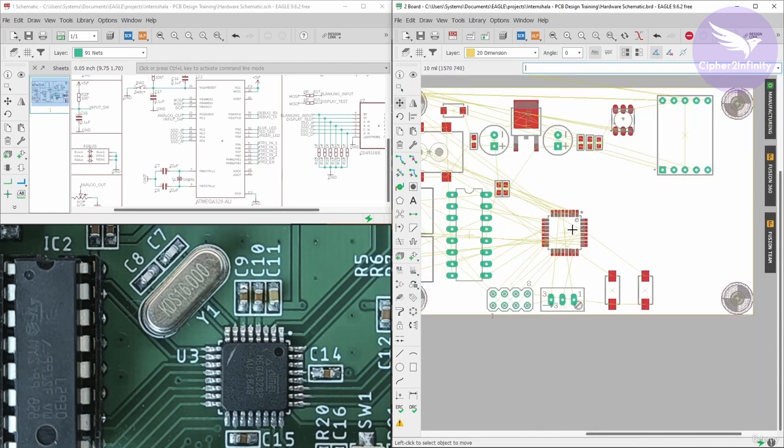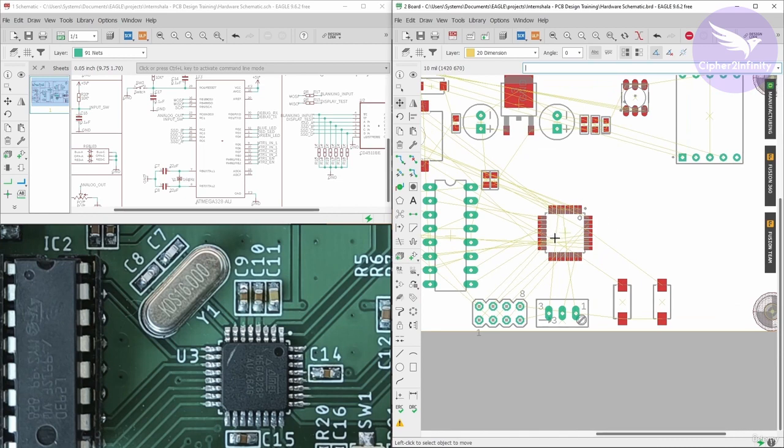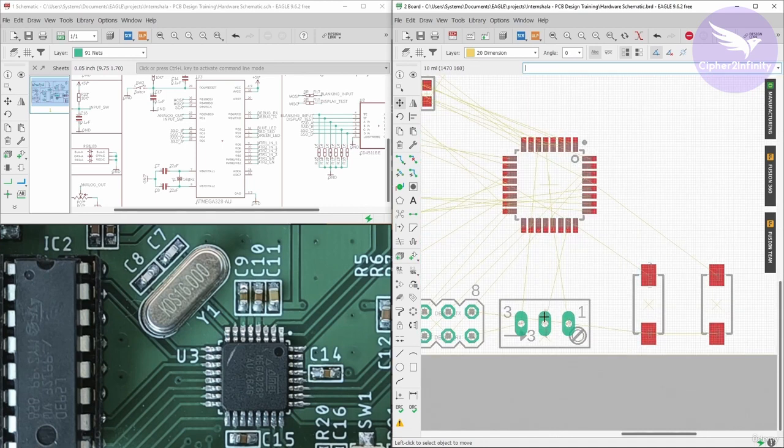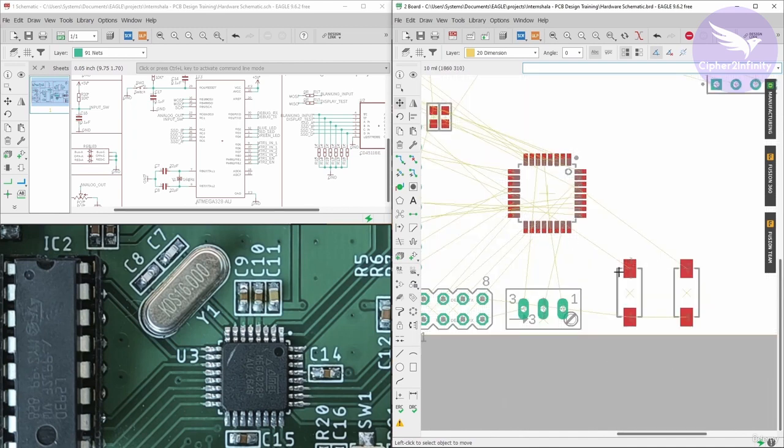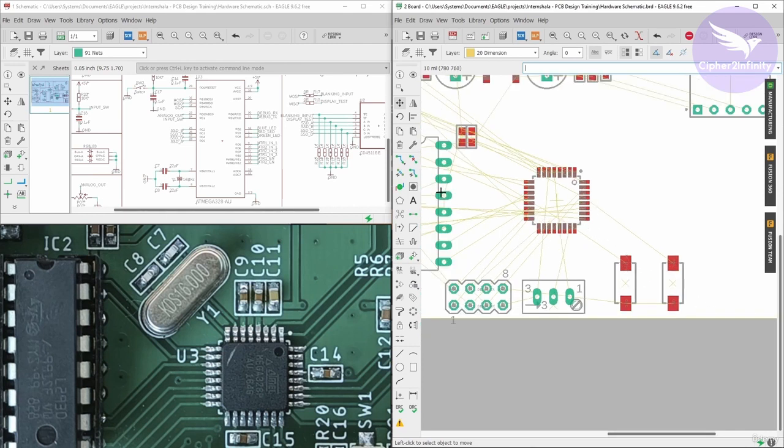Also, one more thing that I want to tell you here. Sometimes while selecting the orientation of this controller, you will find that none of the orientations helps you resolve the connections or simplify the layout. In that case, we know that the position of this preset is fixed. This preset will be here, and these 2 switches will be here. So we can choose the analog pin from this controller on this side, and choose the digital pins for the user input switches from this side. Likewise, you can make changes in the schematic while you are creating the layout.